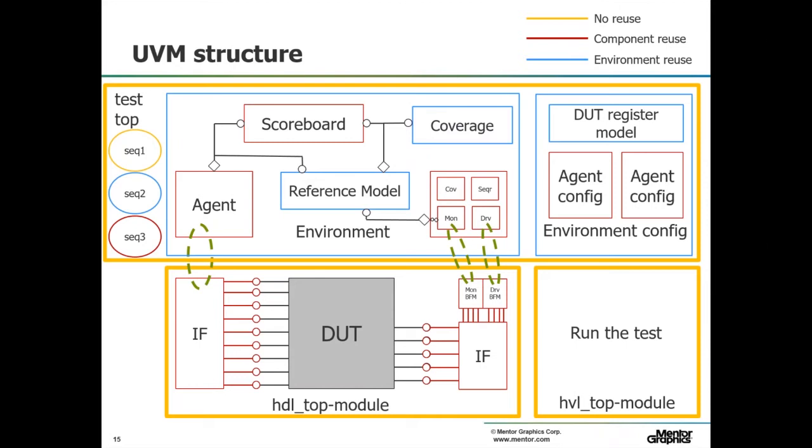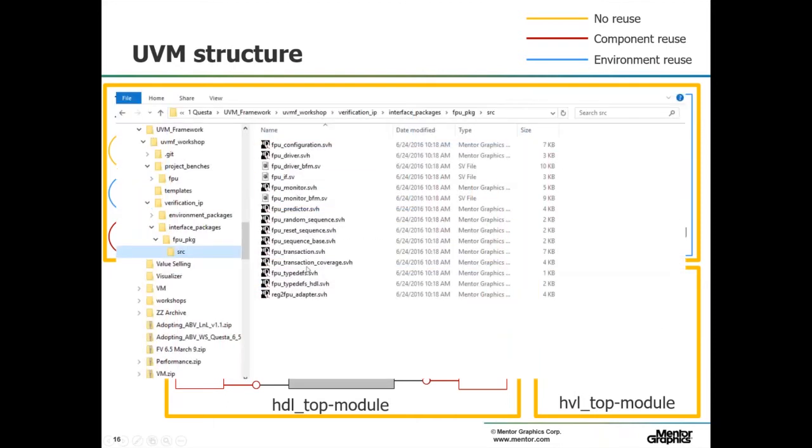The scoreboard is there. So the problem with UVM is, even though it does set up this methodology, set up all of these vanilla pieces for you, it's a lot of code and a lot of files. So every one of these agents is going to be maybe half a dozen to a dozen different files for that agent. So there'll be one for the monitor, one for the driver. There'll be a driver BFM. There's the sequencer stuff. There's all of these different things that you have to create for each agent. And even on that other test bench, there's two of these agents.